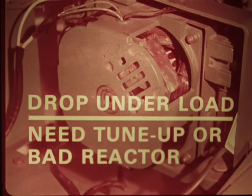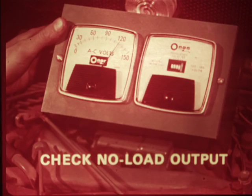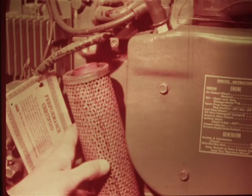Now let's consider a generator that's unable to pull a load. A big drop in output under load can indicate that the engine needs a tune-up or that the compounding reactor is bad. If there's an obvious drop in RPM under load, start your diagnosis by checking the engine tune-up items. So first, be sure the no-load output is to specifications.